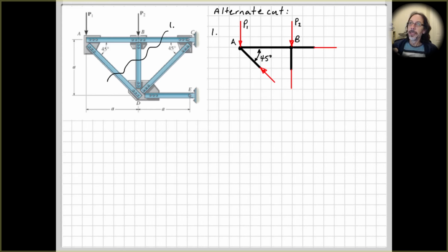Okay, so that gives me the sense of one of my unknowns. Then looking at our other forces, apart from the unknown force over here, the only other horizontal force is the horizontal component of this force that we've just found. It acts to the left, so therefore this one up here must be to the right. And if we take moments about point A, this force here is pushing downwards, causing a clockwise moment, so therefore this force pushing up here has to be causing an anti-clockwise moment. So therefore that's why it's upwards. Right, give them all labels. Apply our equations of equilibrium.